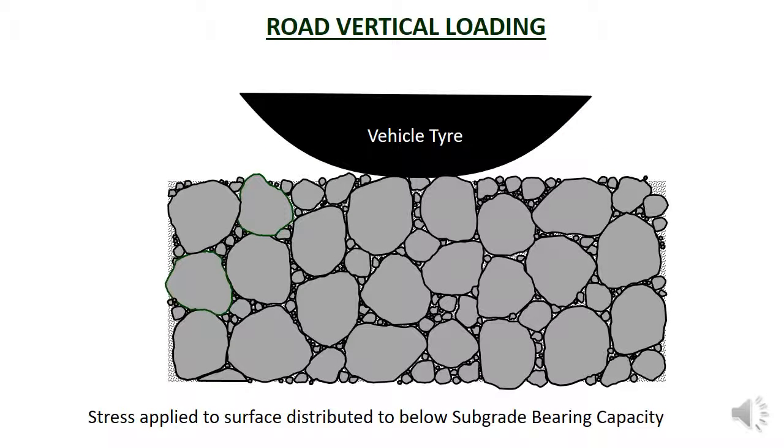The roads we're looking at are flexible pavement roads, which is what almost all New Zealand roads are. The road loadings are supported and distributed by the base course, then the subbase, and then the subgrade. The base course and subbase are unbound granular pavement layers. This means the aggregates are not bound together and rely on the interlock between the particles to hold the layer together. This is different from other engineering materials.